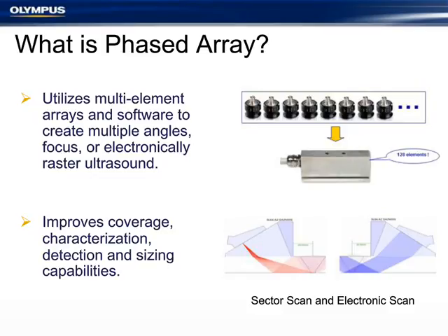So basically what we do is, instead of having a single ultrasonic crystal like we would with conventional ultrasonic testing, we basically group many different elements and put them into a single housing, as we can see here. Typically those are varied from 16 to 128, but throughout the history, and some very complex arrays for more scientific or in-depth testing, arrays have been made with over 1,000 different individual elements. Some people familiar with NDT might think of paintbrush transducers, a little bit different concept. Instead of just physically putting probes next to each other, we actually have each one of these individually wired and have the ability to control them in groups instead of being isolated individual elements.